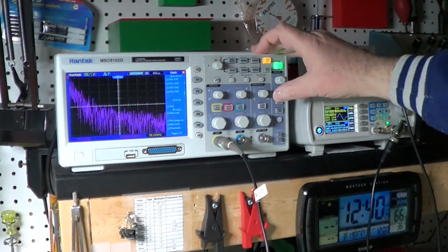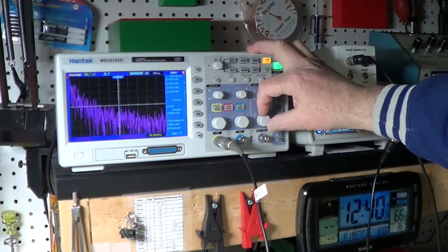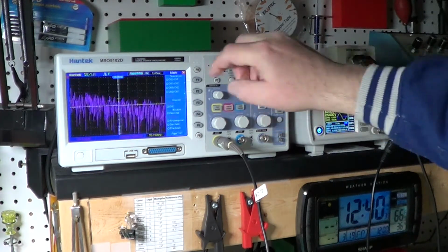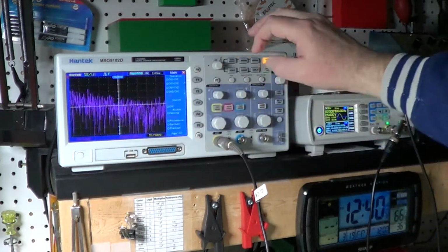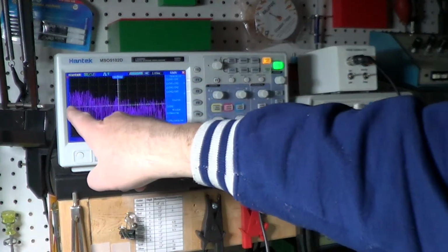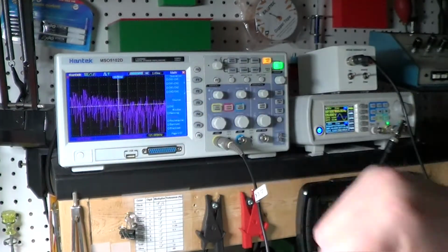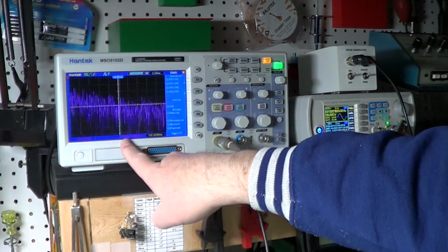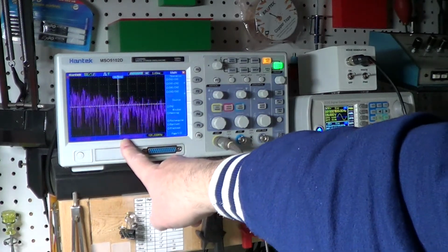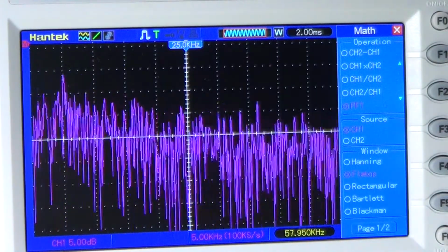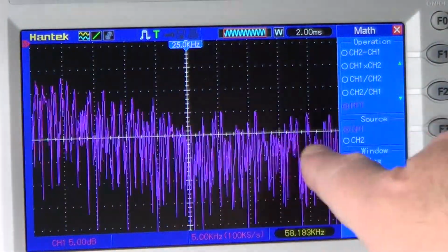Let's change the scale now, so we can try to figure out what is the cutoff frequency of this filter. As you can see, I'm reducing the range of frequency across the screen. Now I'm taking just the first 25 kHz, from 0 to 25 kHz. And each division is basically 5 kHz. So you see, the oscilloscope gives me a bunch of information in here.